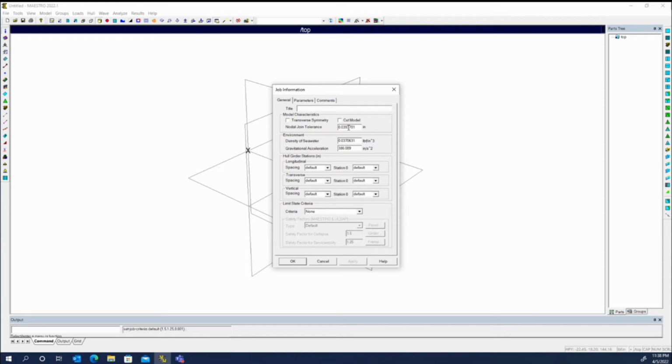When you're doing the modeling, Maestro tracks everything internally with what it refers to as an FE tag, a finite element tag. So every node in the model, every quad, every tri, each element that's created has its own unique FE tag in the model. And if you have multiple coincident points in space, they all get assigned to the same FE tag. When Maestro is running the analysis internally, it's doing everything with FE tags. To present the data to the user, you would inquire based on the module and which quad it is in there. You don't directly interact with those FE tags.